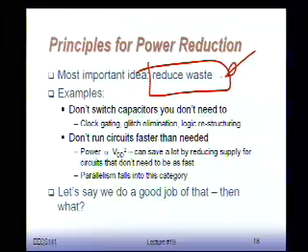They didn't care. As I might have mentioned already, take the example of the first Pentium processor that was released, the first Intel Pentium, around 1990 or something like that. It was kind of funny, kind of embarrassing for Intel, but that processor was using the most amount of power when it was executing NOPs, no operations. Which was ridiculous, right? You don't do anything, you just feed NOPs through the chain, and that's when you were really peaking on power. Everything was flipping back and forth randomly, so they created a lot of random effects. They figured that out quite rapidly. The next generation, they did a much better job on that. But it was clearly an example of waste.